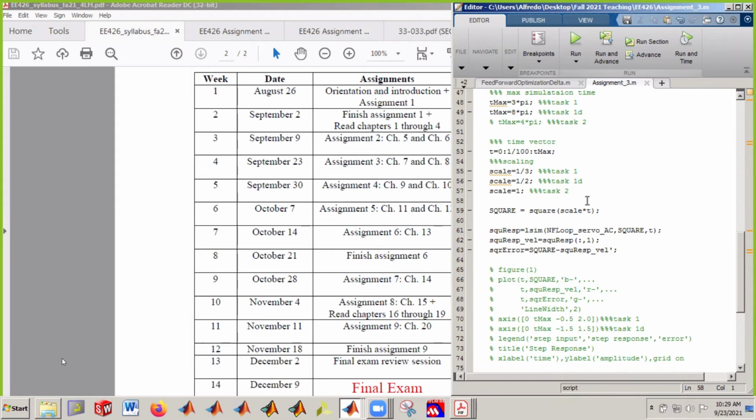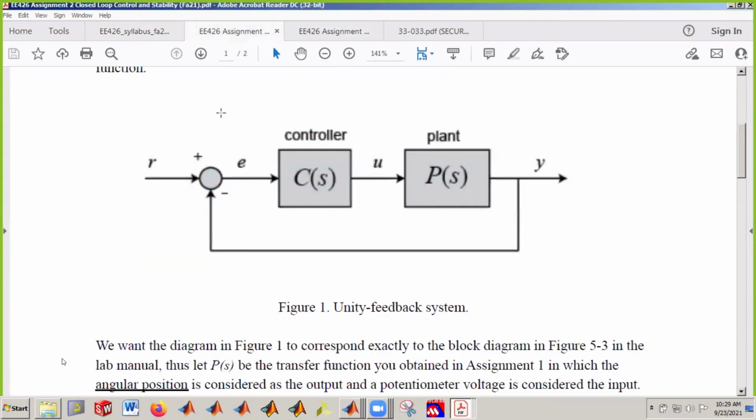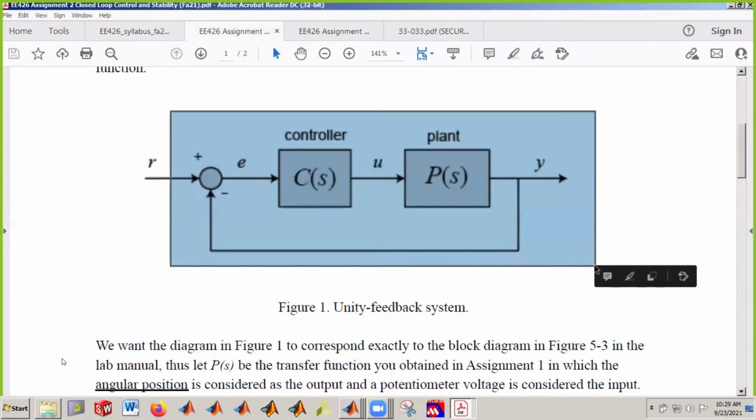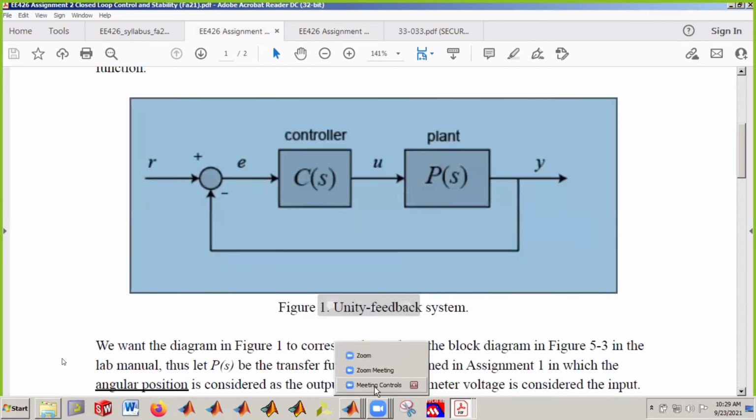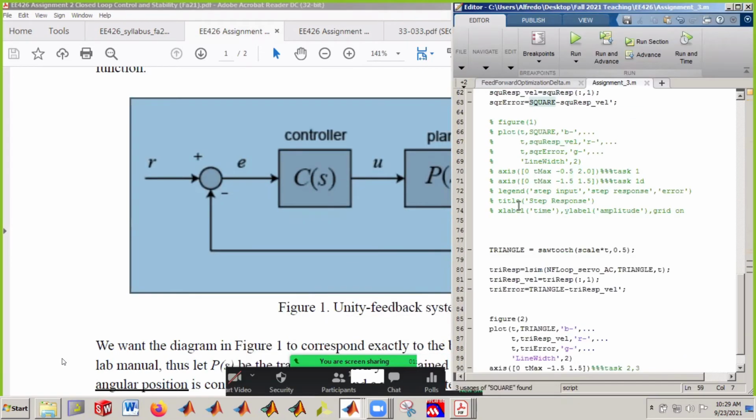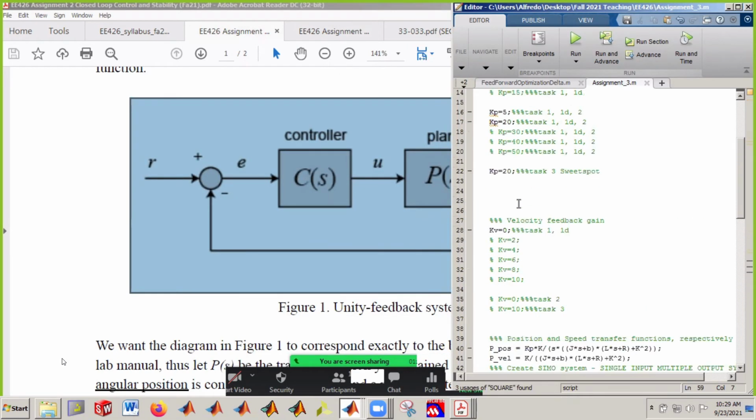All right. So this is what you call adaptive controllers, because if you think about what we have been doing, right? This thing is an adaptive system in itself. So I hope all of you understand what the question was. Our classmate was wondering, can these things change dynamically? Can you have this system change? For the setup that we have, we choose a KP equals 5, we fix the KP, and then we study specific values of KV. So we are never dynamically changing the value of the gains once we choose them.